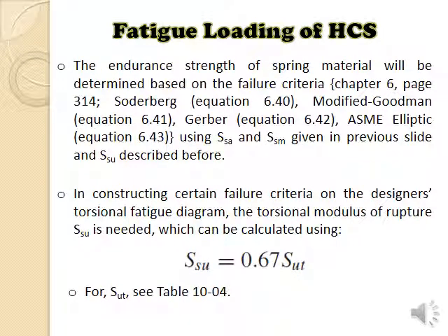To identify that, here it talks about the torsional modulus of rupture, which is nothing but 0.67 of S ultimate, and S ultimate you will get from table 10-4 in your book.